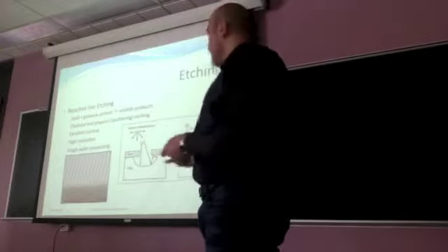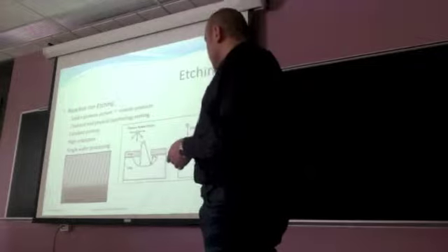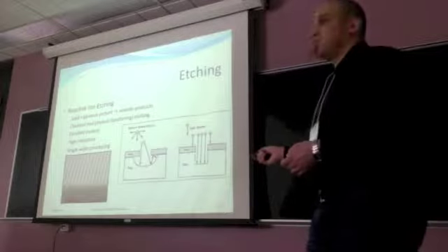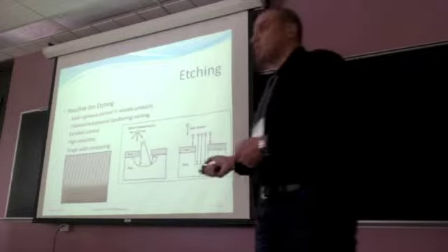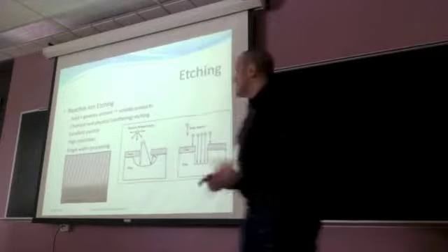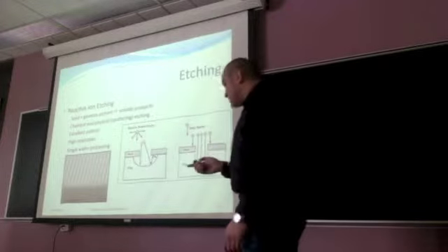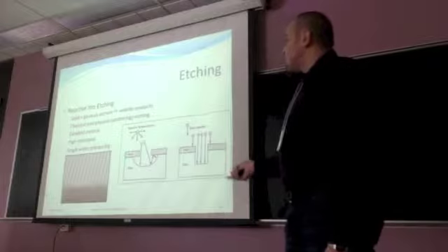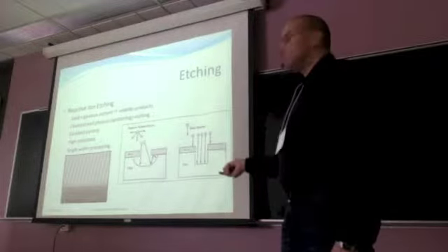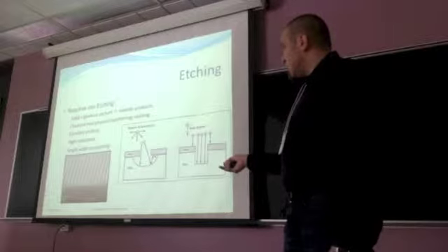The reaction between a solid and gaseous etchant results in volatile products. There are two components in reactive ion etching, the chemical and the physical ones. The chemical etching is responsible for isotropic etching of material. So you can see the typical curved profile when material is etched isotropically.